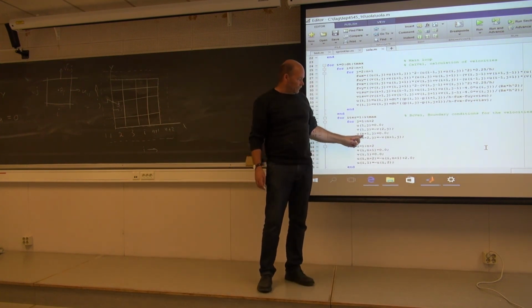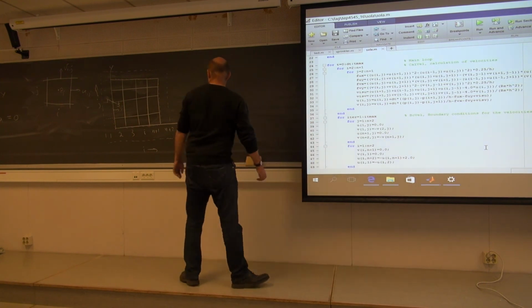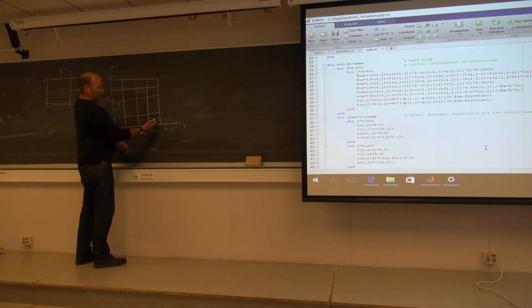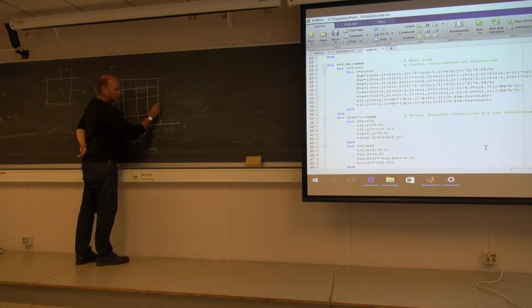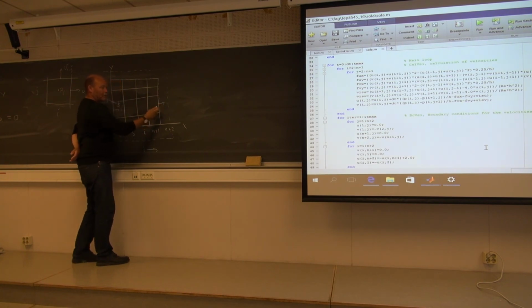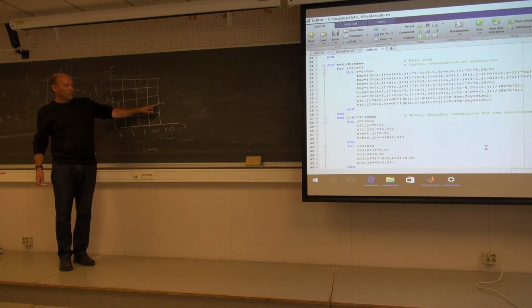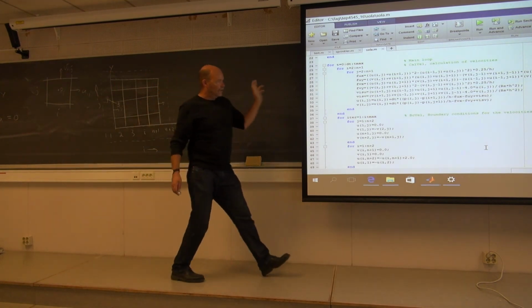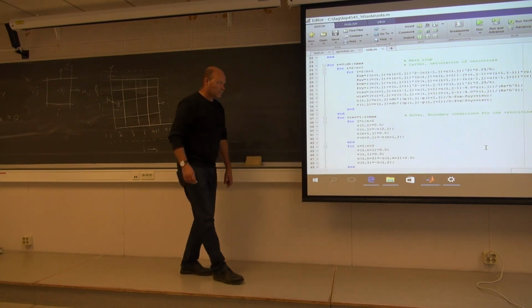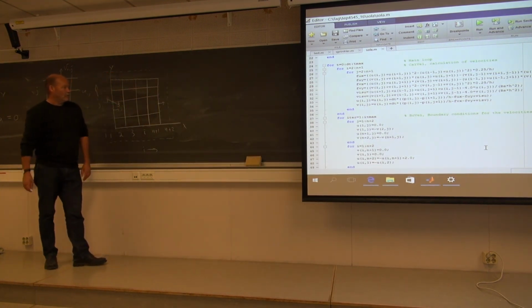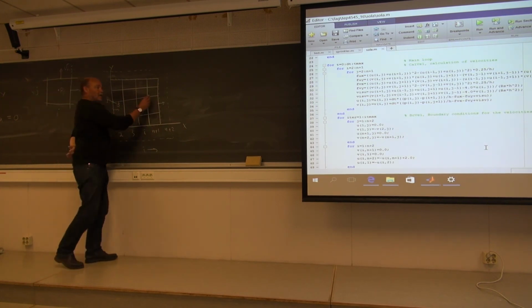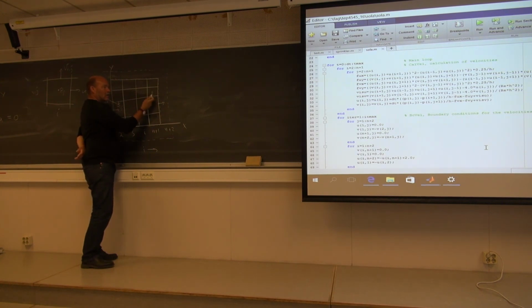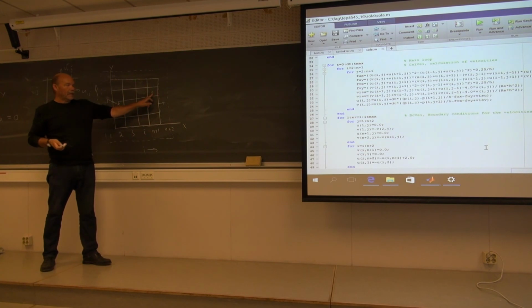On the other side, un plus 1. Which one is that? Well, n plus 1, that's these cells up here. And u for these cells, well, that's to the right. So here we have un plus 1. And perpendicular to a solid wall, of course, he is 0. No problem. What about v? Well, the v velocity for cell n plus 1, well, he's located here. But he's a live velocity. He's supposed to be calculated from the Navier-Stokes. He's not part of the boundary conditions.